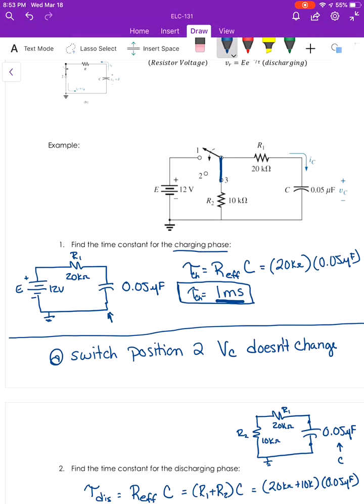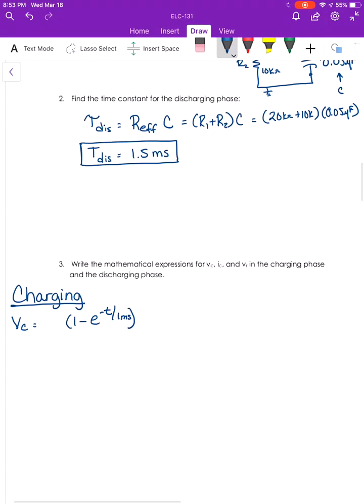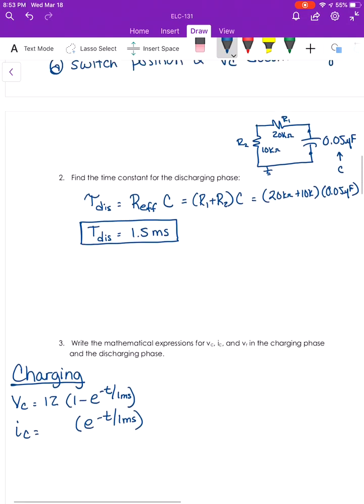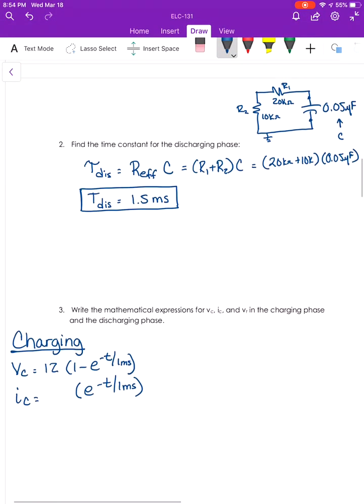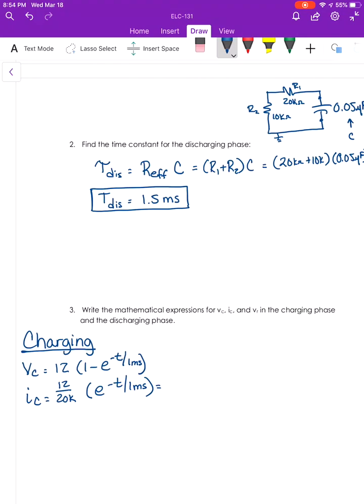Over here is our circuit. When this becomes an open circuit, we're going to see 12 volts across that open circuit. That's going to be the open circuit voltage, and that is what our capacitor is charging to. I sub c, remember that current is always going to start at a maximum and go to 0, which is what the shape of this equation gives us. And what is that current? It's going to be 12 divided by 20,000 ohms, which is about 600 microamps.